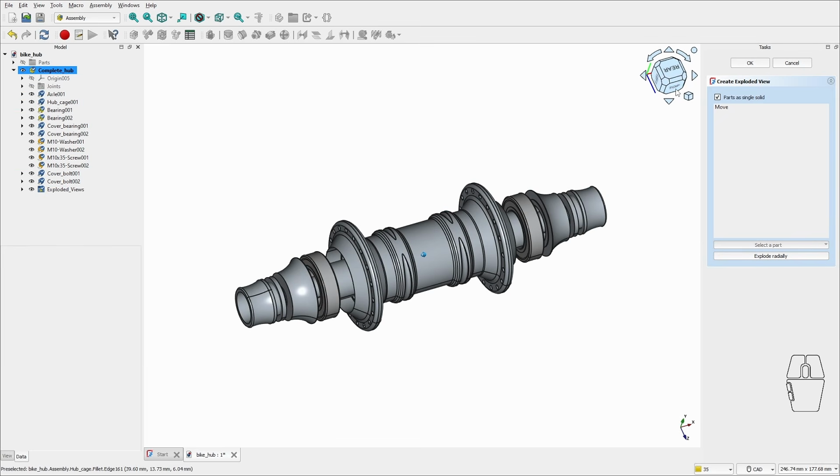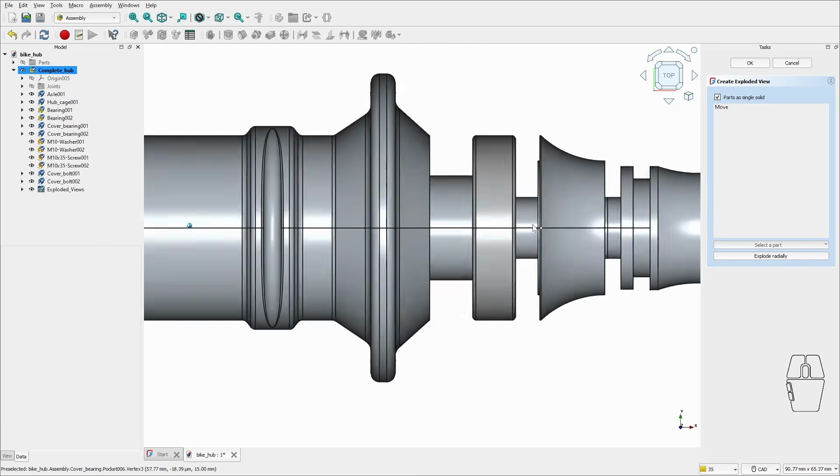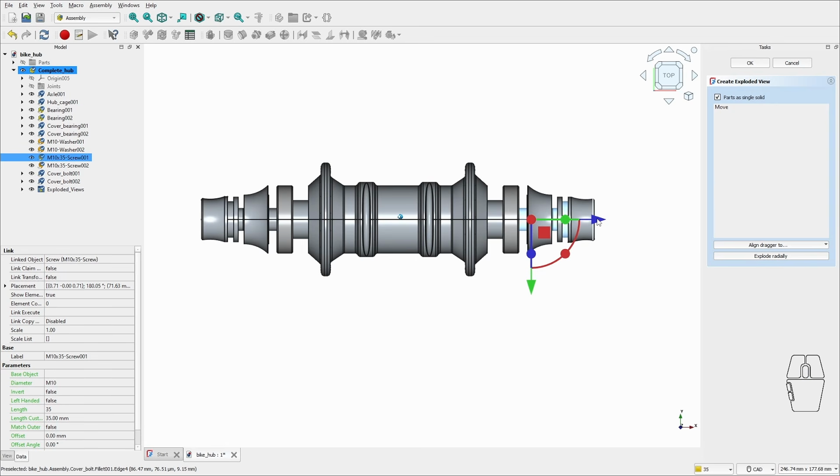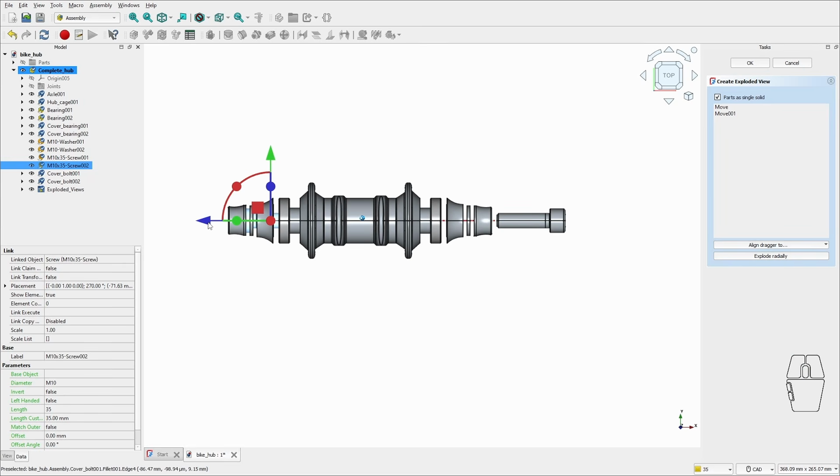You can switch to the top view for a better overview of your exploded assembly using the view cube in the top right corner of the screen. You can move each piece individually by selecting them in the viewport and using their dedicated gizmo to place them wherever you want in space. For my part, I move the bolts so they are more detached from the assembly, and I also subtly move the bearings so they are less attached to the other pieces.